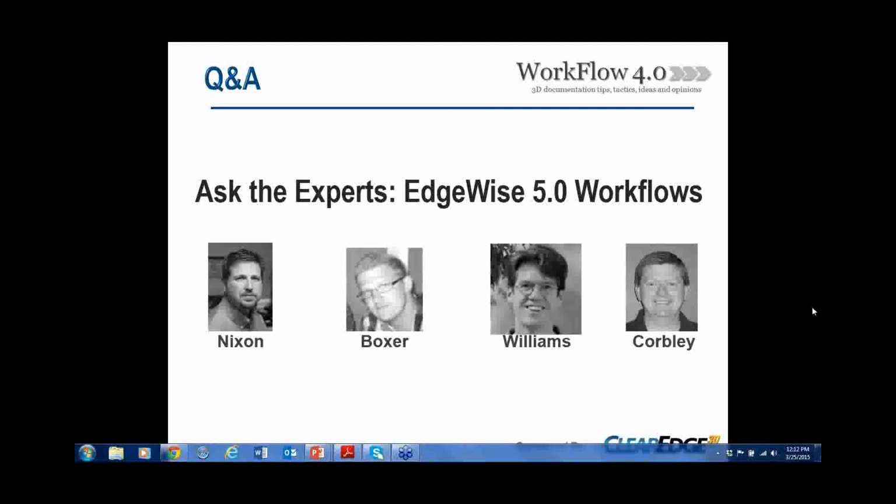Okay, and we're just going to take two or three more real quick ones here. Kevin, does setting scanner density higher limit false positives and help clear edge extractions work easier? Yes, to a degree. Really the more important thing is to get better coverage though. You need a minimum density for a pipe, but if you can get both sides of the pipe, that's more valuable than scanning the heck out of one side of that pipe.